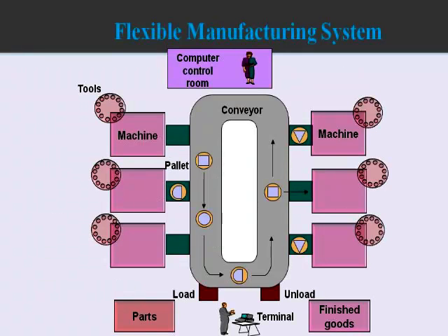You see this flexible manufacturing system. The workpieces are transported from the loading station to these machines as per the process sequence, and the required CNC programs are downloaded as per the movement of the parts among these machines. The part programs are downloaded and the parts are routed as and when a particular part reaches a machine and is placed on the machine with the help of pallets.